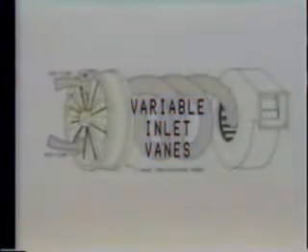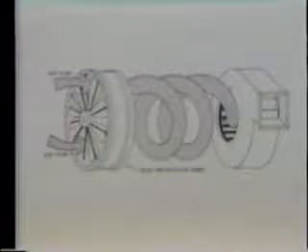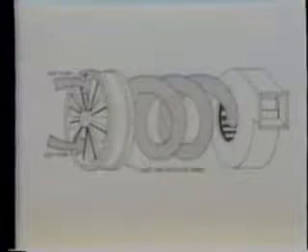The next option is variable inlet vanes. They are the most commonly used method of controlling fan capacity on variable air volume systems. Inlet vanes, often referred to as pre-rotation vanes, cause the air to swirl before it enters the fan wheel. The fan wheel cannot grip the air as well, and consequently capacity is reduced more efficiently than with discharge damper control. Excess pressure is not created and wasted.